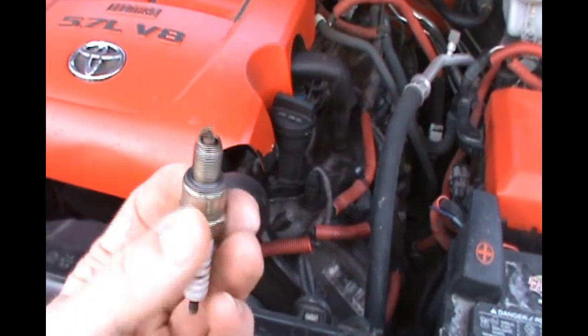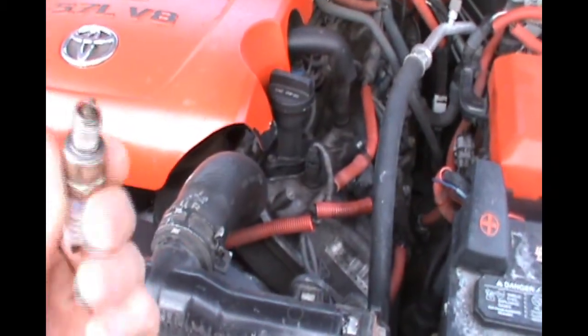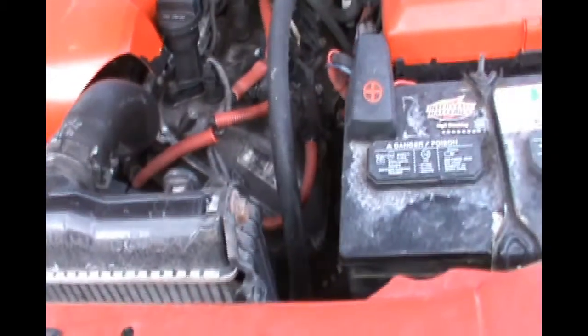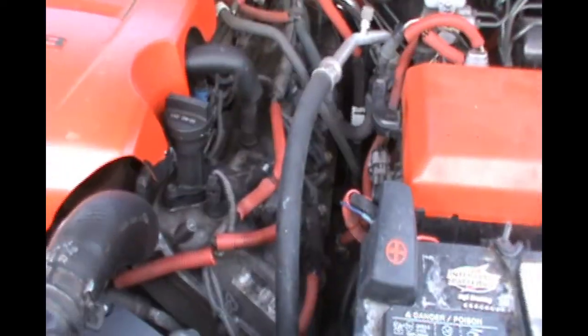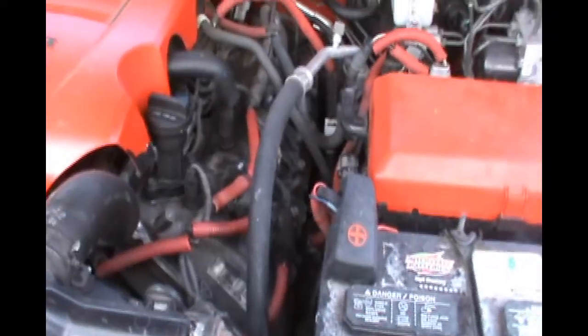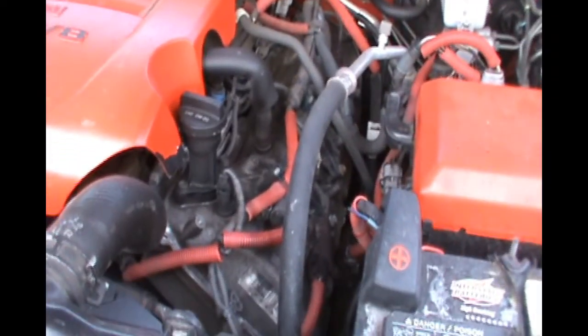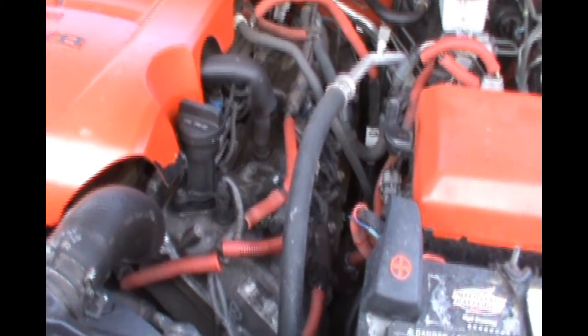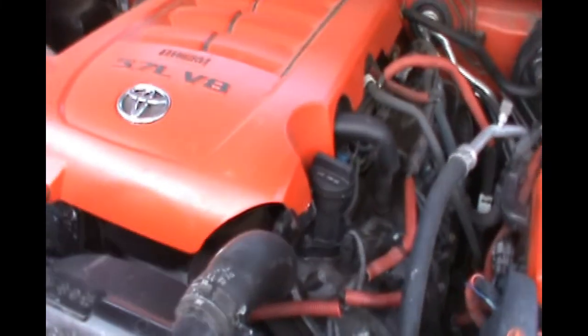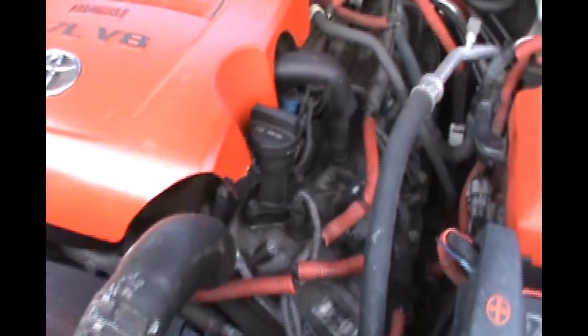Once you have the spark plug out, you check it to see if it's in the right heat range, to see if it's the correct color, and most of the time in automotive vehicles they are, unless you have any performance modifications like a cold air kit or anything like that. It's more important to double check, especially when you do any type of performance modifications, exhaust, intakes, any type of supercharging or turbocharging, or running different fuels that this vehicle wasn't called for, like higher test fuels.